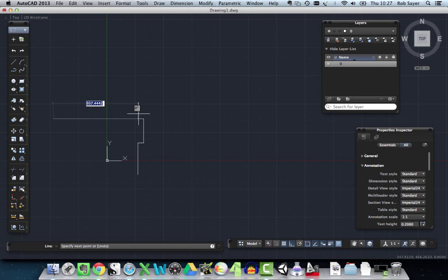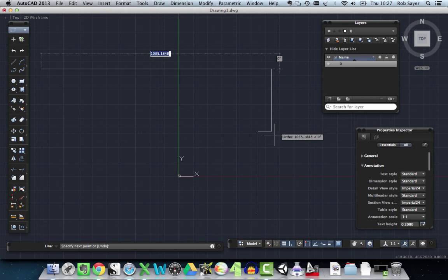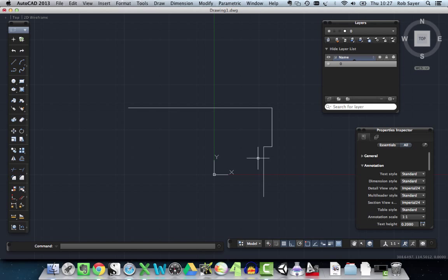And you can see what's happened now is that I've got 4 lines, but I started this line, having finished the line itself, in exactly the right place using the snap. That's a key part of using line, because eventually you'd want to join all these objects to make them into one big long line. And that takes us back to Polyline, because in some ways what I should have done, if I wanted this to be a single object, is draw this as a polyline, because eventually I might want it to be one single object anyway.